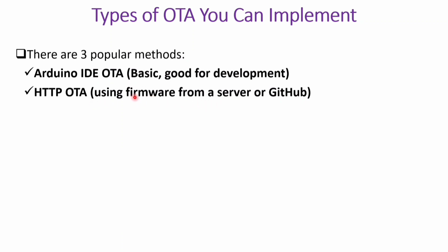So in this approach, you are going to write firmware and save the firmware binary file onto a server like GitHub or Google Drive. With the help of this approach, you are going to trigger that firmware update and load the code inside ESP32. So it is very much practical. You can also automate the firmware update process, and with this method, you can manage many devices, many ESP32. For example, if you want to update the firmware, it is possible with the help of this approach.